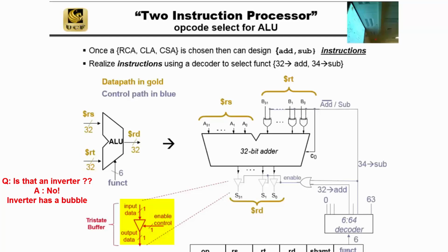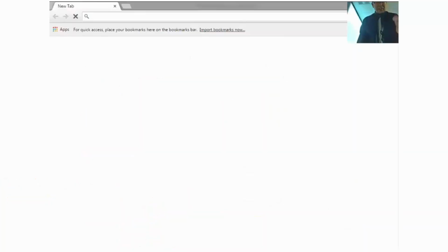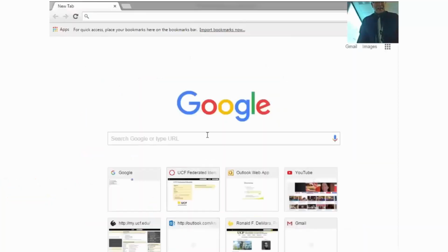Now the interesting thing is, if it's A input to output, this is A to not A because there's a bubble. But then you're going to ask, why do you need this? Because this is electrically isolated. The electrons on this side of the triangle are not the same electrons on the other side. There are different ways to do this. You can do opto-isolation: they convert it to light, and they use a photodiode to convert back to electric on the other side.